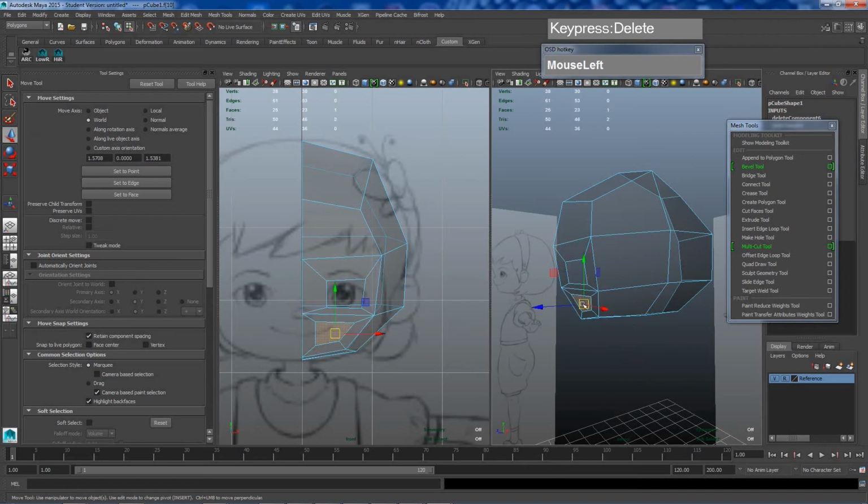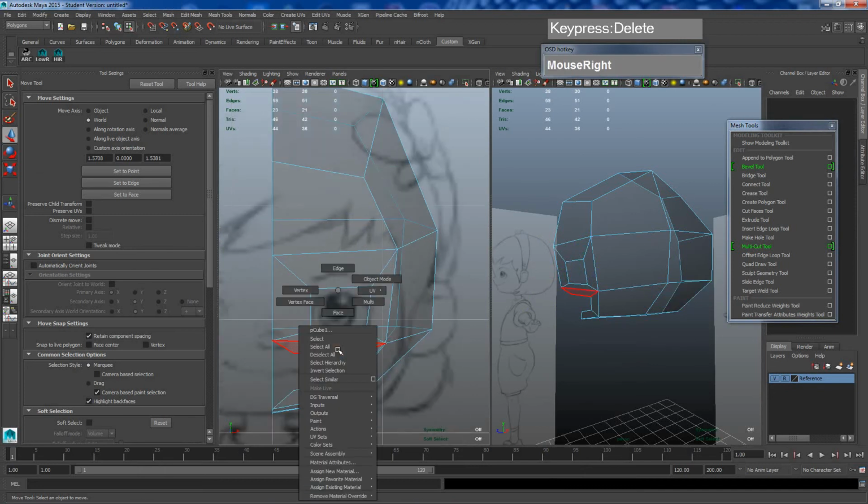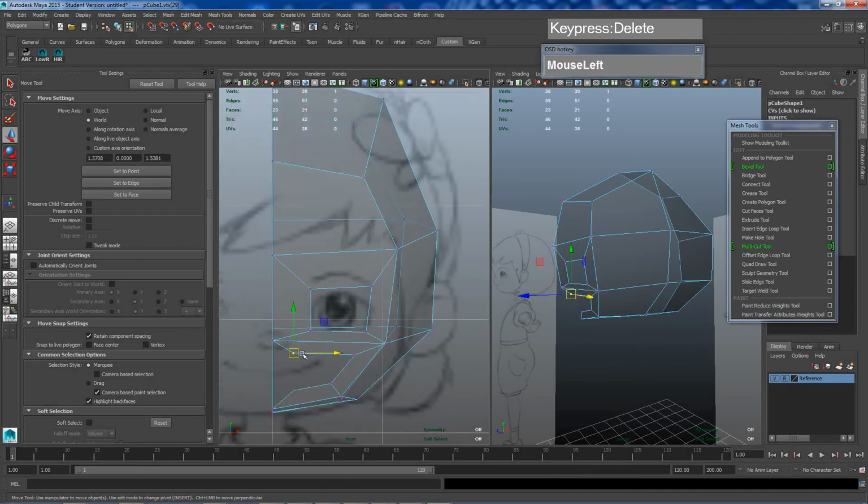Select the bottom faces, that is covering the mouth and also the adjacent face, and then hit delete. Alright. The next step you need to do is to right mouse click, go to vertex level and start to move these vertices. I'm going to hold down Shift X and then move it until it snaps to the origin location. And then I'm just going to move this upwards until it covers the mouth, like so.